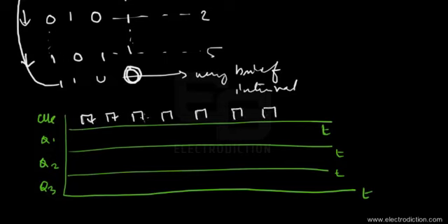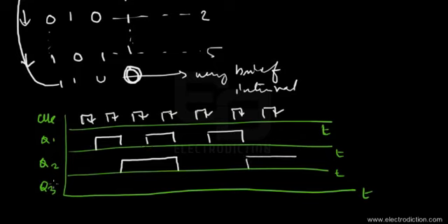On the negative edge of each clock pulse, the output of Q1 switches to logic level 1 and falls down again upon the arrival of the negative edge of the next clock pulse. Whenever the output of Q1 falls down, the output of Q2 goes up and continues till it encounters another negative edge from the falling output of Q1. This goes on, and finally Q3 goes up when it encounters the negative falling edge of Q2.